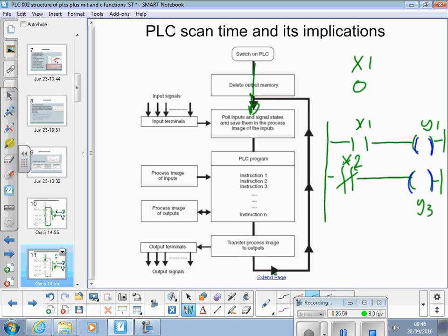At that point that's off, and this step is number 100 down the line somewhere, not the first one. So it's done all these other instructions. In the time between going from step 0 to step 100, after it has recorded that that switch is off, X1 actually turns on in real life. So here's the real life X1 over here, and it goes to 1, on.